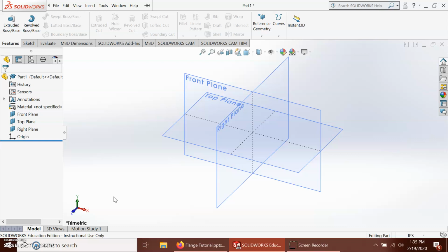Why is this important? A couple reasons. When you go to put this into an assembly, you need to know how to measure it from where it's going to be and where the part is going to go in the assembly. So you always want to have everything tagged back to the origin, back to 0, 0, 0.